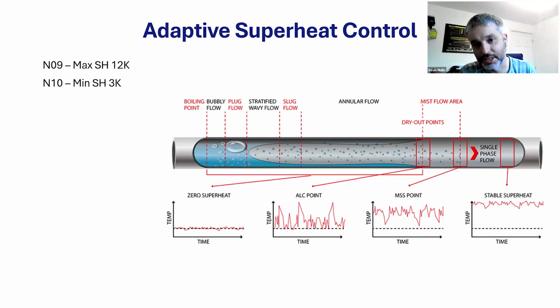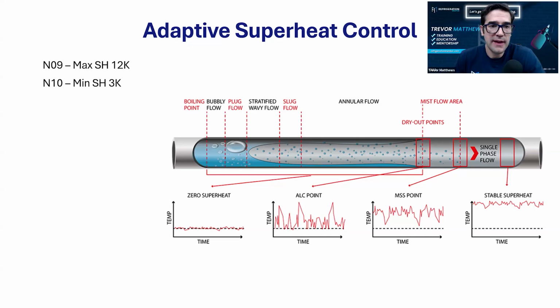Yeah. But Danfoss is quite good. It will adjust the superheat to get the most out of your coil. And this is in Kelvin so anyone doing superheat in Fahrenheit, you would multiply that by 1.8. So 3 multiplied by 1.8 would be like 5 degrees superheat.